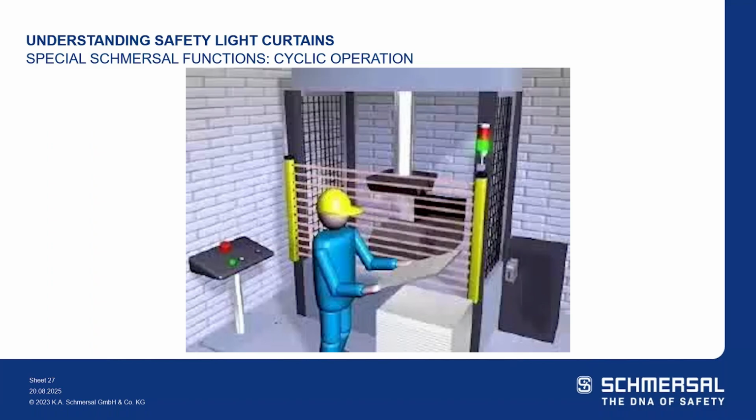The programming of the machine expects that protected field of the light curtain to be interrupted between machine cycles to either place the item or remove materials, or maybe to make an adjustment. So the machine will initiate the next cycle once the beams are restored. That function should not override the primary function of the light curtain. If the protected field is interrupted during the machine cycle, the hazardous motion is stopped and the machine is put into an interlocked state until the safety has been reset.